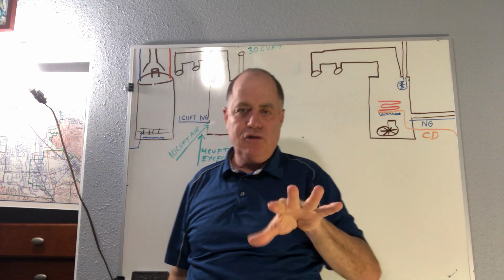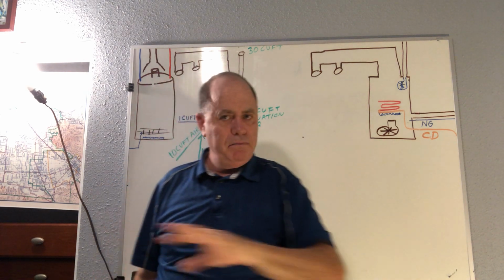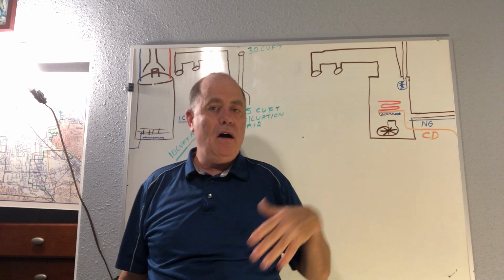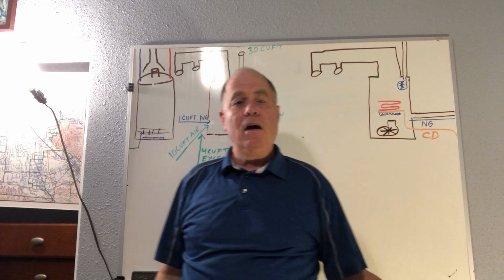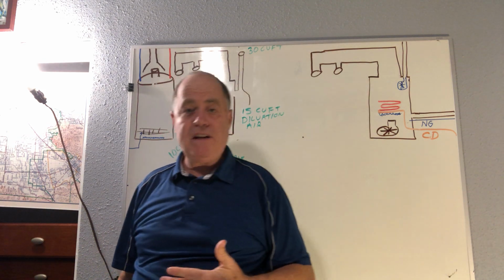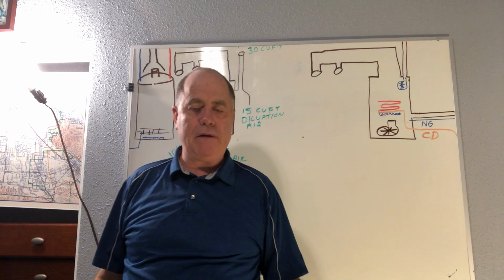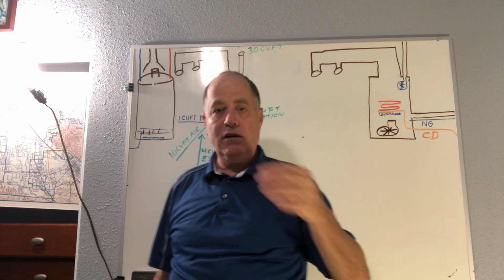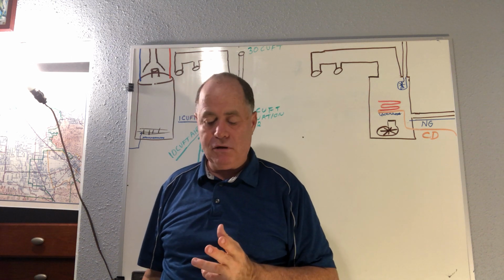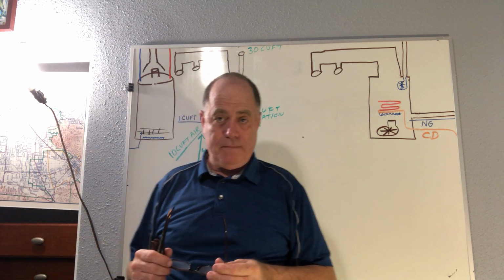And you always have to, here's another general principle for combustion air, you always have to have a source of air, essentially fresh air that can go and feed that. You can't starve your appliance. You have to have the right mixture of air and natural gas, and we're going to get into that in a minute, to have proper combustion.